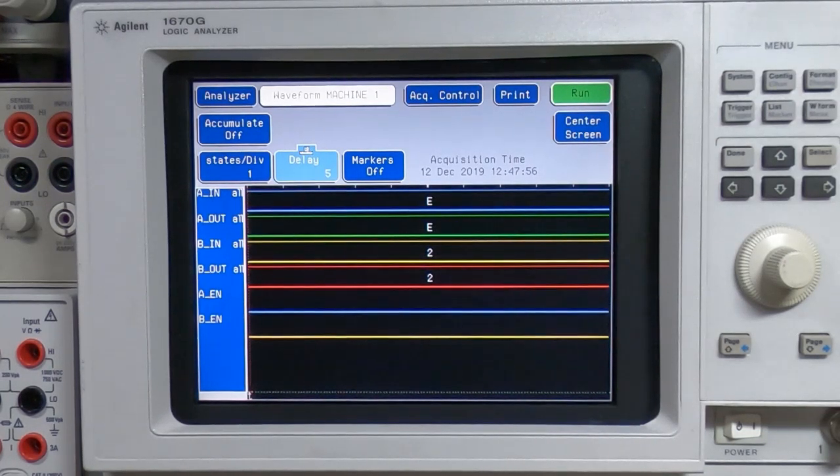And what I can do now, of course, is move the test clip to the next 244 and test that one as well. In fact, I've been around the entire board and that was the only 244 that was showing any problems. What I'm going to do now is to move on to the 245s. They're actually far more likely to cause issues because they're bidirectional, and so if there's a problem in controlling them, you can end up with contention on the inputs or outputs of them, and that can damage them.